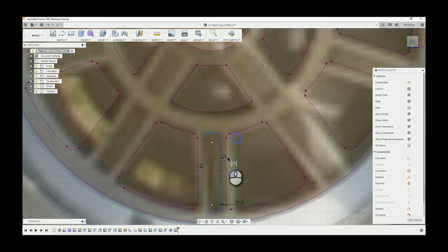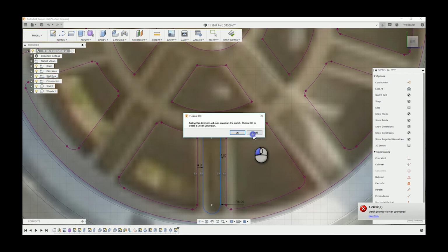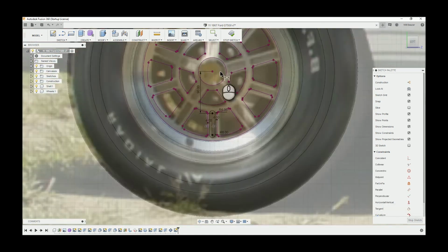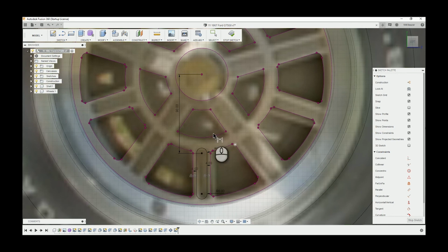But I could have used the slot tool. In the sketch drop down, there's a tool called slot tool, and that would have created the exact same shape. So again, it's just knowing different ways of doing things, because you're usually finding in CAD that there's probably about 5 ways to do everything you do, and it's about picking the right way to do it. And I'm fairly certain in this process so far, there have been some things that I've looked back on and thought were pretty questionable.